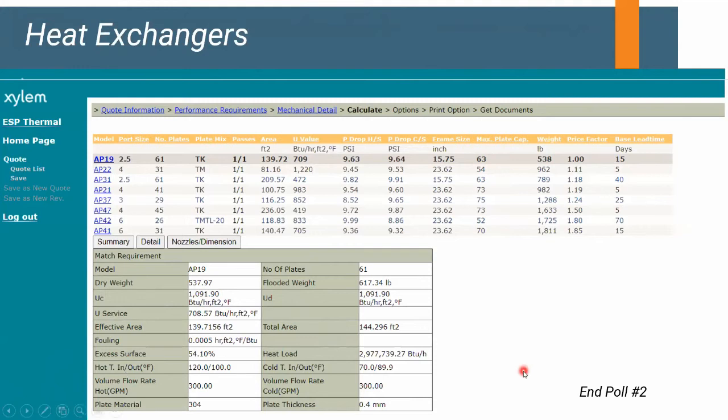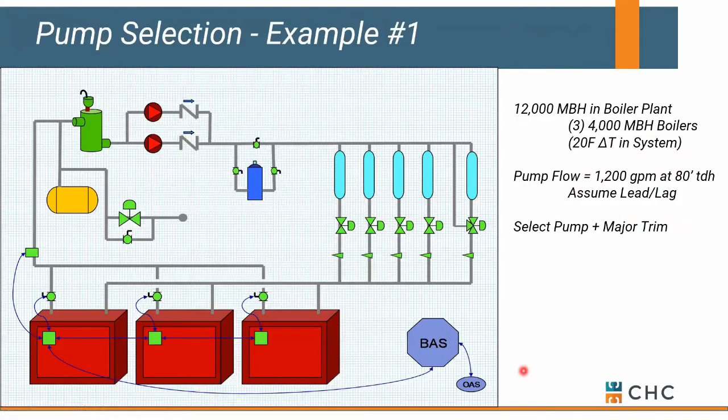Okay. Got it. Let's bounce into software for a second. Again, we're 20 minutes in, so we're doing pretty good so far. What I did was pull a sample schematic that we've looked at before. Maybe 2 system pumps rolling out through the system, bringing flow back through our boilers as far as variable primary goes, or primary only. So the system flow is handling the flow through the system as well as through the boilers.